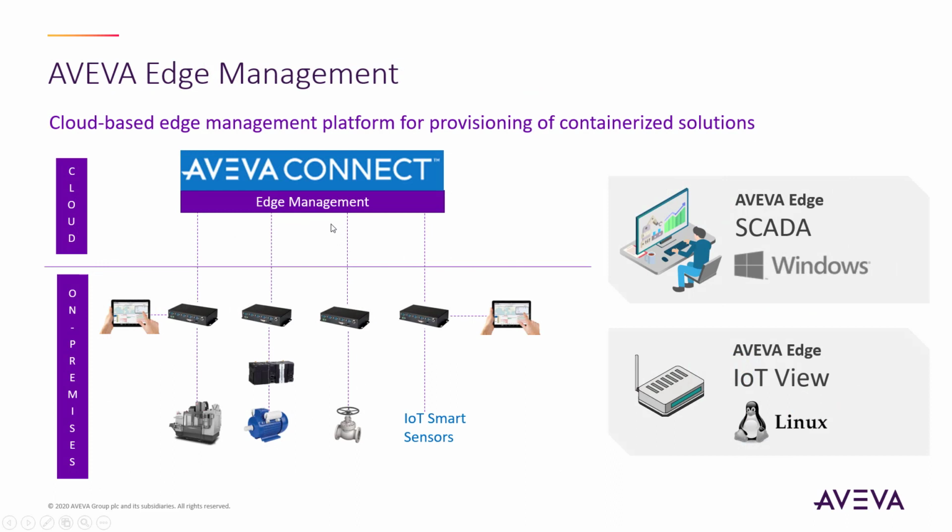So a unique tool that is available for AVEVA Edge is something called AVEVA Edge Management. Now this is a cloud-based deployment tool, if you will. So what it allows you to do, rather than connecting up to individual PCs or HMIs on the plant floor, is deploy your project through the cloud and let those devices go get an update to the project, to the runtime version, even the license from the cloud.